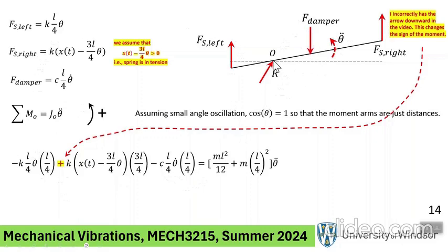And we're using the parallel axis theorem in order to find the I about O, and the way it works is that remember, for a rod, if you assume this is a rod, the mass moment of inertia about the mass center is ml squared over 12. Okay, but here the mass center is right there, and there's a distance of L over 4 to the center of rotation. So that's why we have to add an m d squared, remember, from dynamics. So d is this distance, which is L over 4.